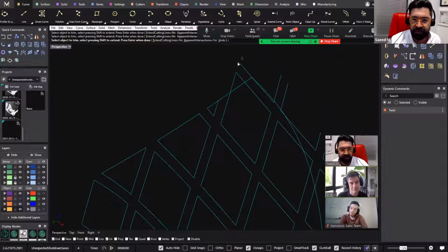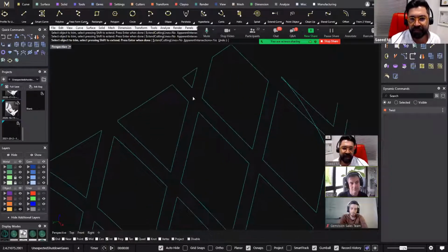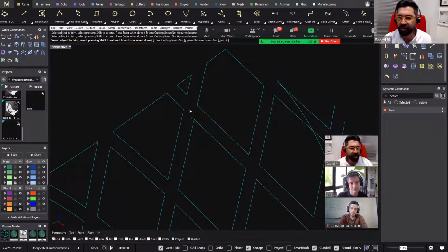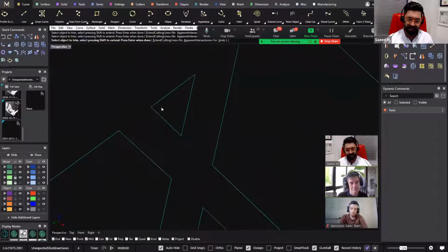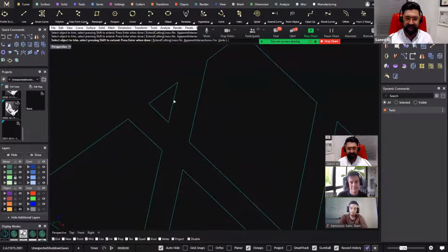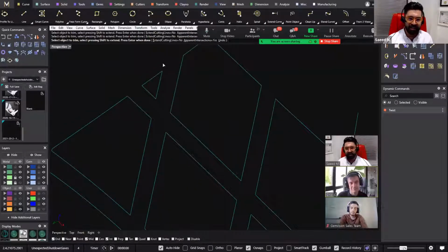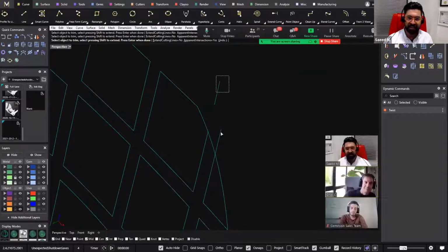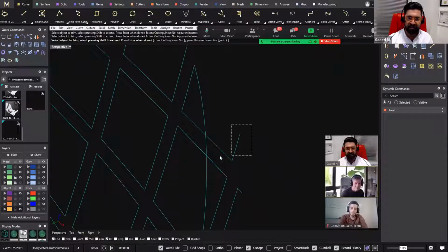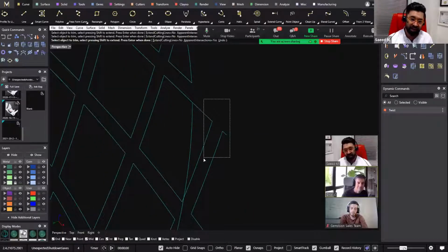There is another important thing for gold casting. When you're making some lace patterns, you're going to have some small patterns like here. And it's not good for casting if it was less than 0.40 or half a millimeter, 1 millimeter. That's why in these cases, we will delete these shapes as well, because after the casting and after the polishing, it just looks like a teeny hole.